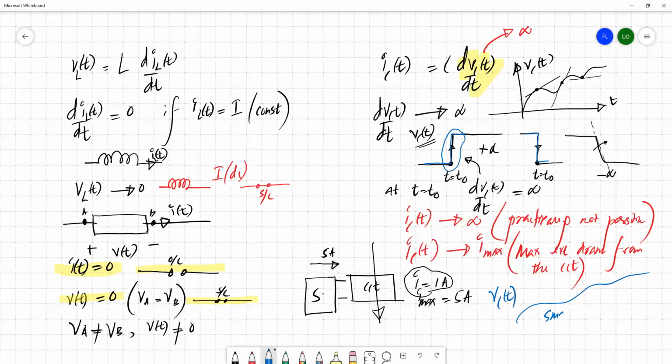Smooth and continuous. So here you can see a kind of discontinuity. Once you come from the negative direction, it converts to this value. If you come from positive infinity to here, it converts to this. So it's a discontinuous situation, and the capacitor cannot manage this kind of discontinuity. Based on that, we can say that the voltage across the capacitor should be smooth and continuous like this.